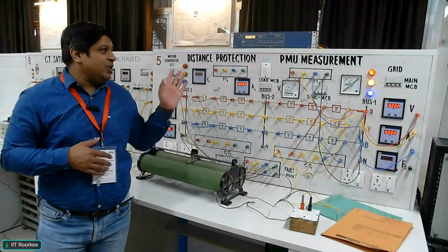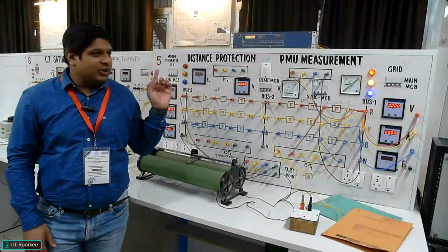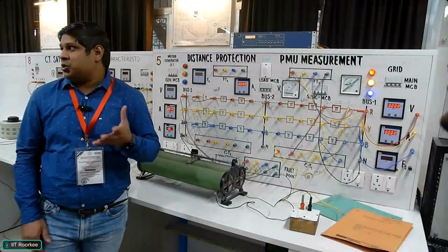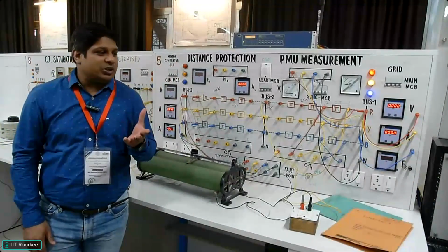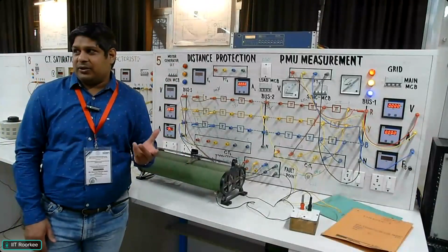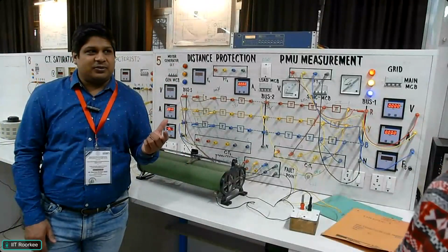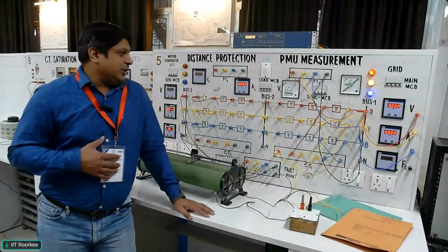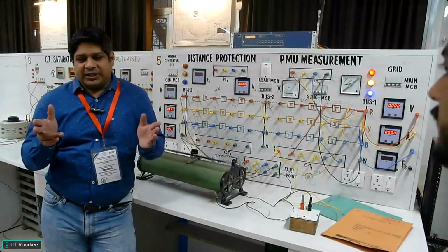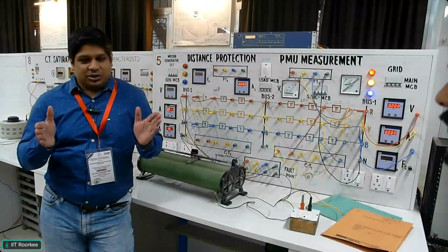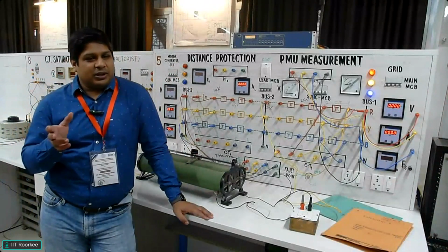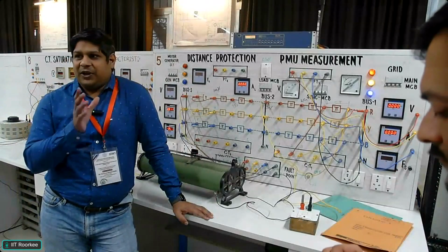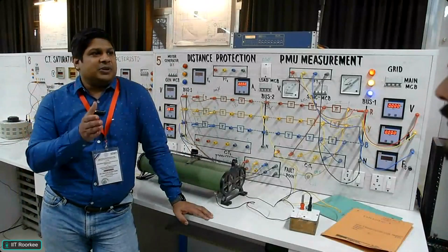Basically we use distance protection in this case. In distance protection, as you may know, we generally use 3-zone protection. Shall I explain? I will give an overview. There is a transmission line, and it has a certain impedance. In 3-zone protection, for the first zone, which is known as the primary zone, if a fault occurs, normally we keep it as 80% of the line.